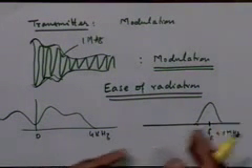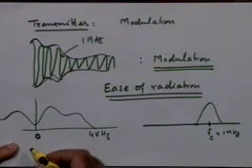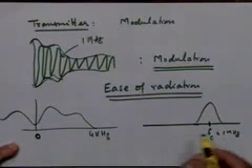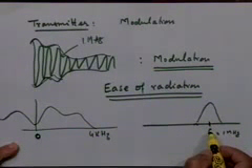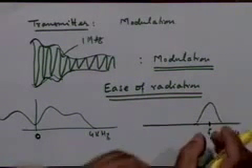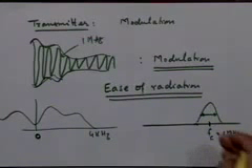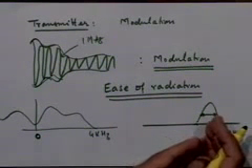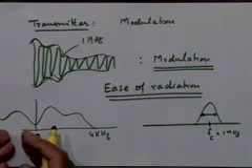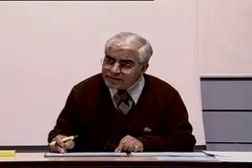So the important point is that the location of the spectrum is not around DC, not around zero frequency, but around some other carrier frequency, some other frequency FC. So we are not increasing the bandwidth. Bandwidth is the span of the spectrum, whether it lies in one frequency band or another frequency band. So you must understand the difference between the center frequency concept and the bandwidth concept.